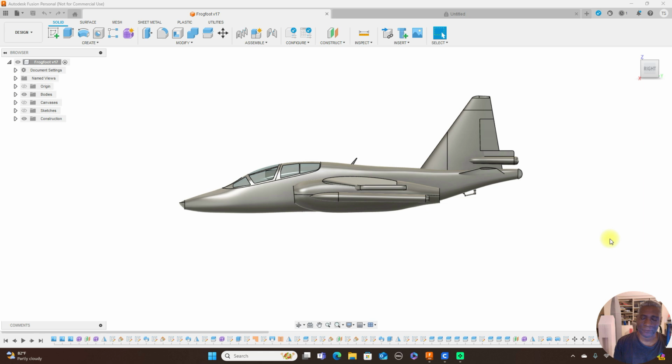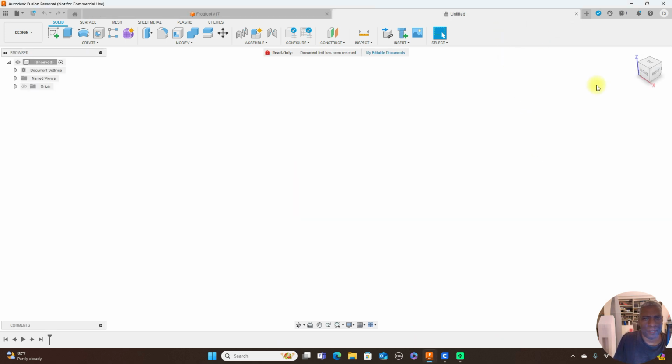All right. Now, the commands that you really need to know. The first thing I would say is planes. The types of construction planes that you really need to know are the plane at an angle and the offset plane. Another plane that you really should be familiar with is the origin planes. So here they are, and you can see those here, these are the planes.